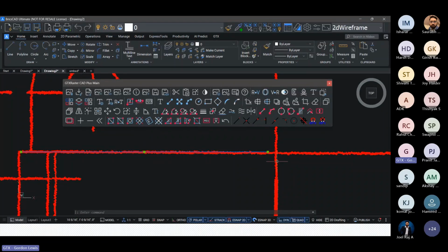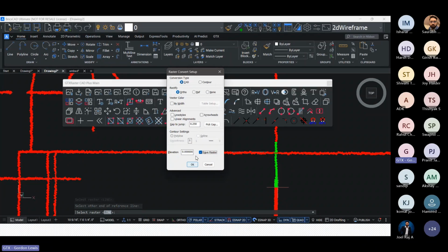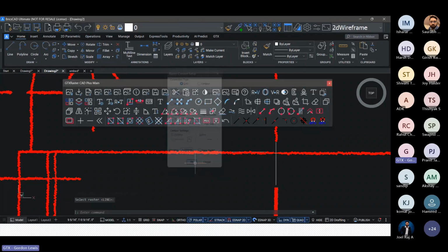So you're actually creating the line from the area that you selected on the drawing. And obviously for that instance, I saved the raster, but if I was to pick another line, say this line from here to here, and say don't save, then it will just draw the new line over the top and take away the old line. Does that answer the question?